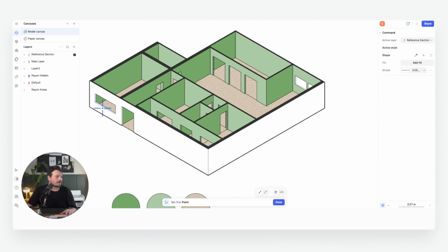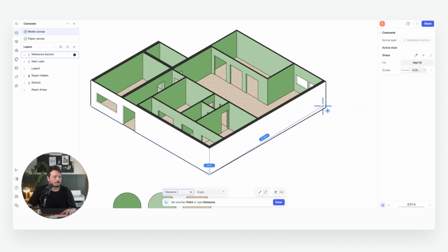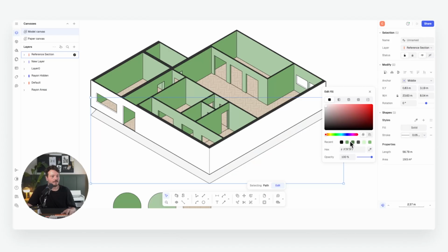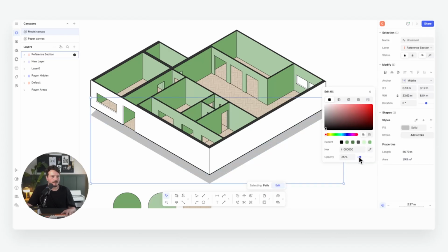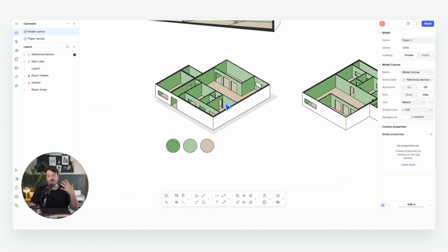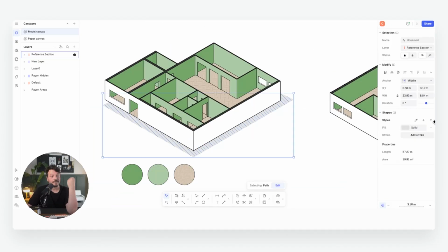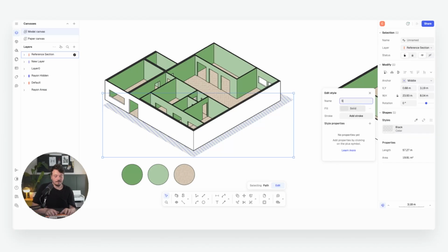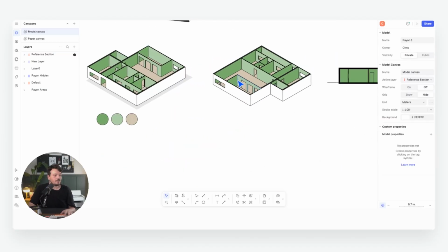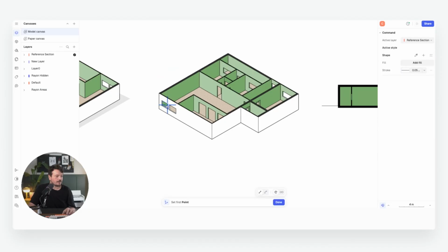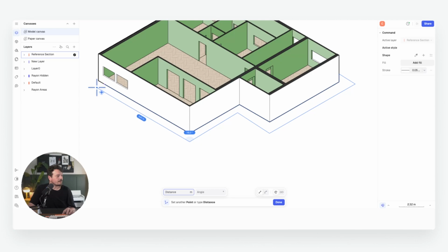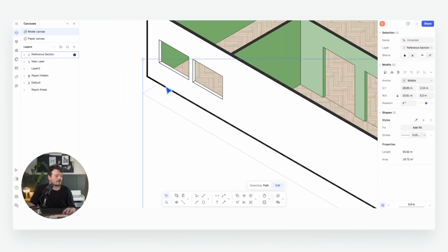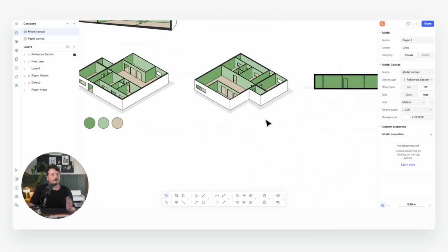Similarly, we could use a shadow, for example. So that could just be a polyline space that really is acting as a fill. We can give that a fill, knock it back, and I can turn off that outline, maybe slightly lighter, 10%. And then that just helps lift it off the page. And again, if I save that as a style, so save style, I'll call that shadow. So then when I go to do one on the next image, I can do exactly the same thing again, polyline. And obviously for the purposes of this, I'm doing everything quite roughly. You can be a bit more precise, and I can pick a style, pick that one. There you go, quick as.